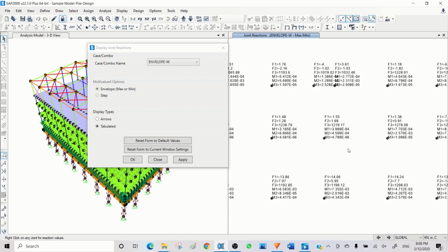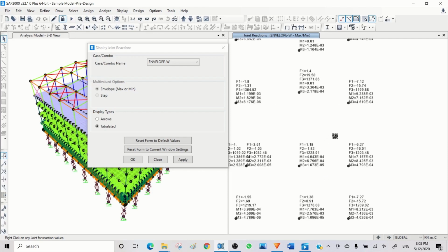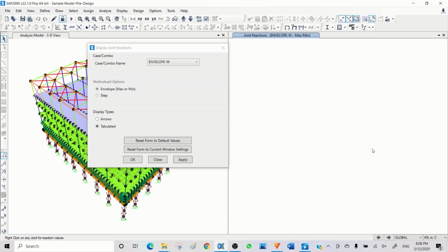Otherwise, I have two options: either increase the diameter of the pile to give me a better bearing capacity, or increase the depth of the pile to have a socket length in a strong rock or soil to give me more skin friction, or increase the number of piles. It really comes back to the difference between the allowable bearing capacity and the load I have, and how much I need to increase it. Is that a little bit or is that too much? Sometimes I need to add more piles to meet the requirement.